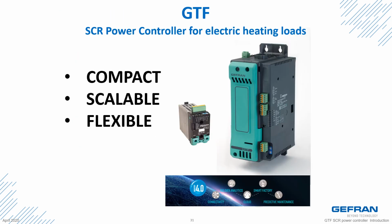In summary, the GTF is a compact power controller. As we saw earlier in the presentation, the GTF power controller is a tightly packaged power controller with a great deal of functionality. It's scalable. The GTF power controller is scalable to meet current application requirements from 25 through 250 amp and voltage requirements of 480 volts, 600 volts, or 690 volts AC. It can be used in single-phase, dual-phase, and three-phase applications.